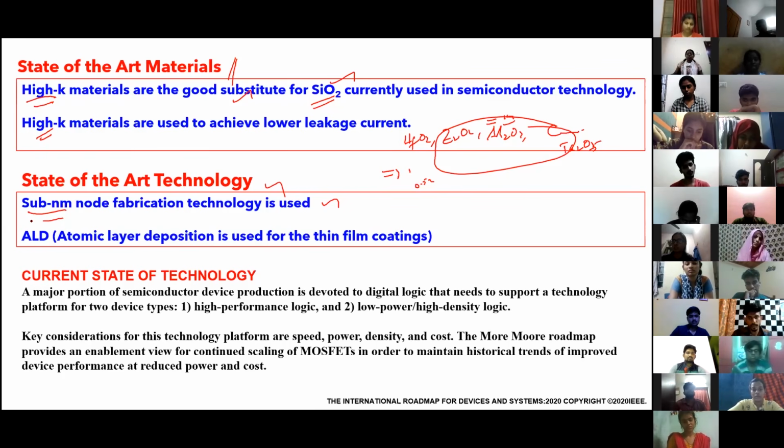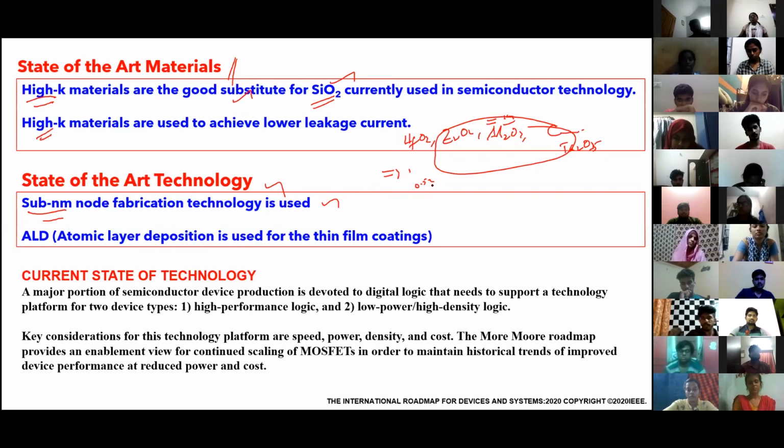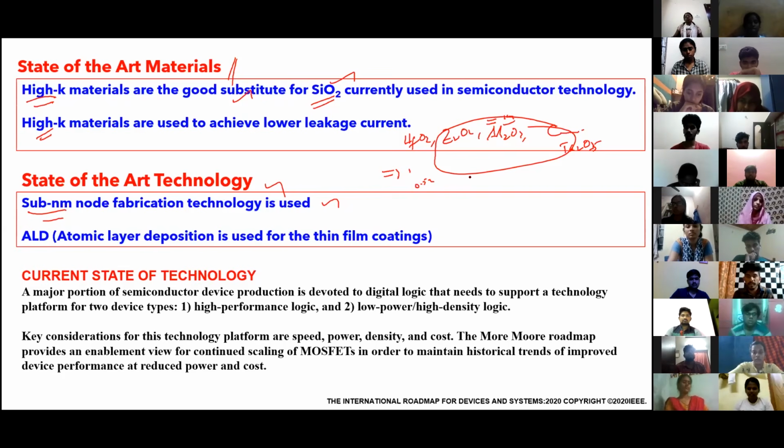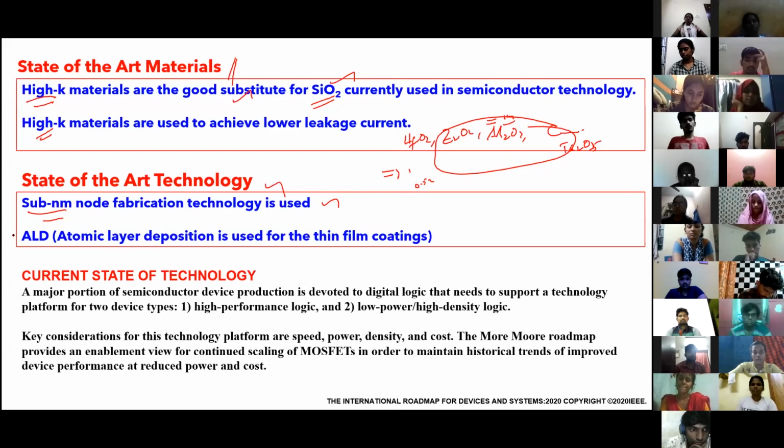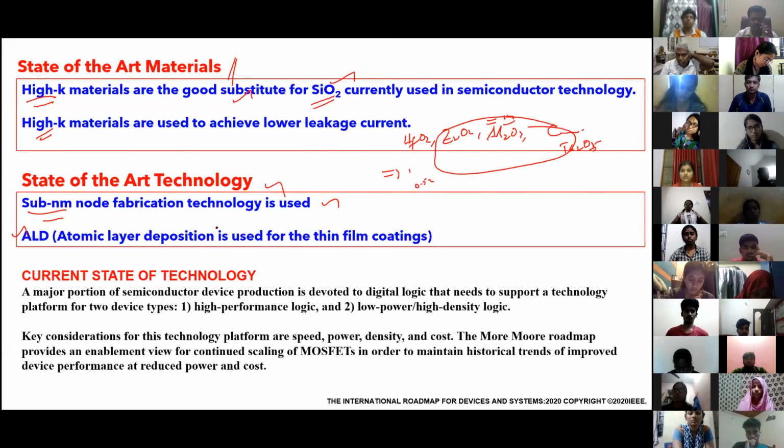This technology was achieved in VLSI technology, so the concentration of components you can make per square centimeter has enormously increased. So miniaturization is still highly possible. And people are recently using ALD, atomic layer deposition, one of the deposition techniques. I did not mention it there, but it's a very popular technique.